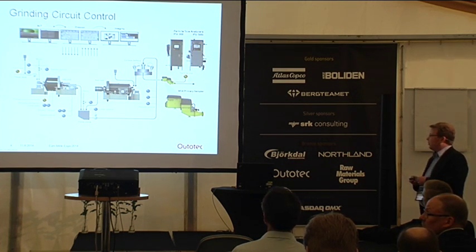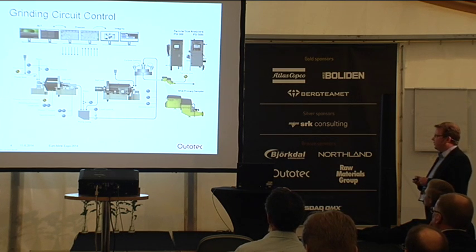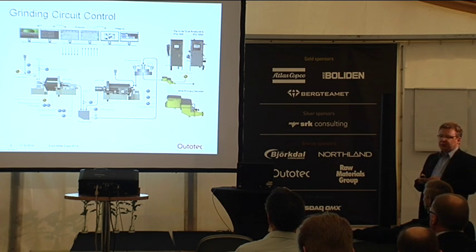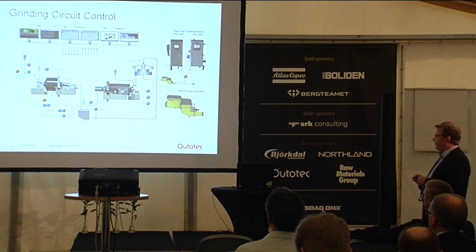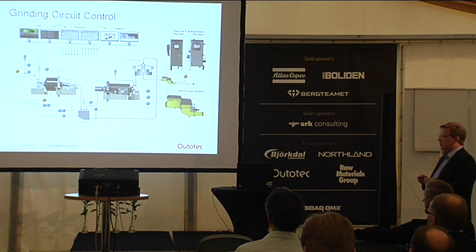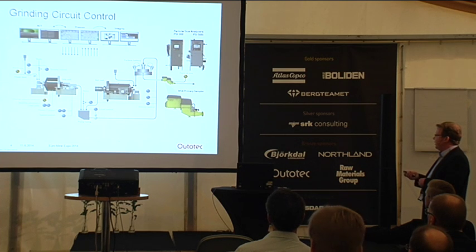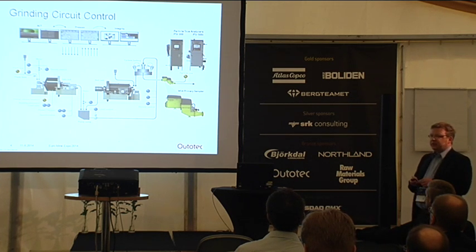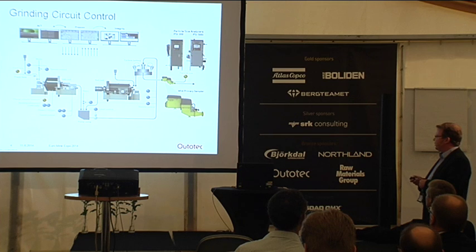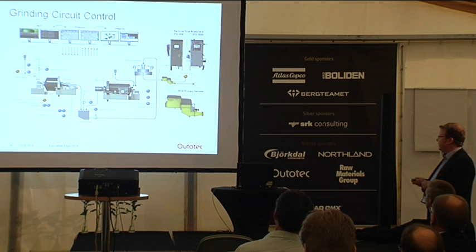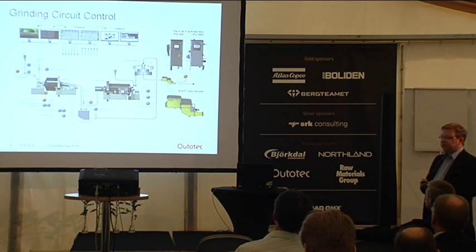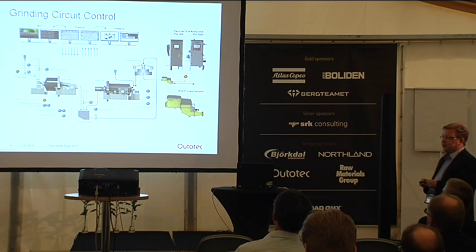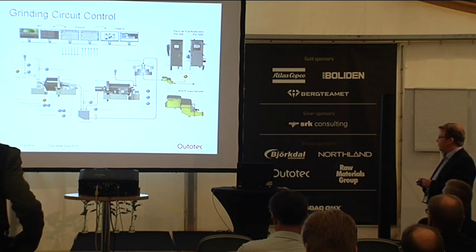Our traditional grinding control solution is shown on this slide. It starts from the instrumentation, the typical instrumentation level that should be available at the grinding circuit, if stabilizing or advanced process controls are reasonable to be added to the plant. There are special instruments for particle size called PSI 300 and PSI 500 from Outotec that are measuring the final product of the grinding circuit. So it is a very important measurement to really optimize and work on the capacity and the quality of the grinding circuit.